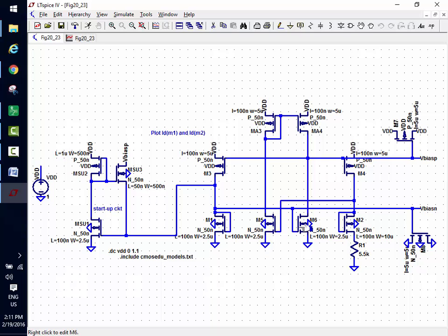So notice, because these two inputs go to the same value, even though this guy is tied over here, it's going to go to the same voltage as this. So don't let it confuse you that, oh, I got two devices here. I want the voltage across these two devices. That's how I derive the equations. I want them to be equal to the voltage VGS1 here.